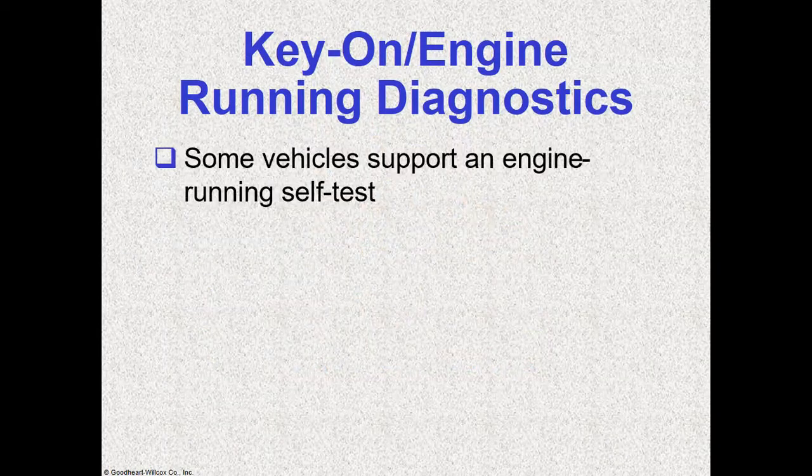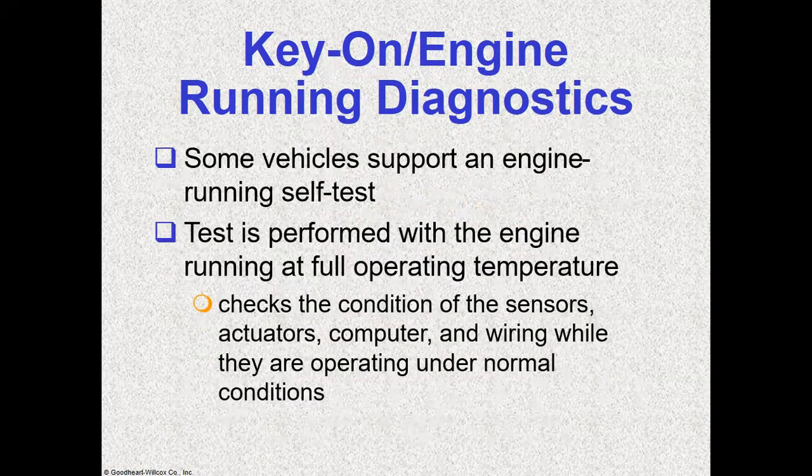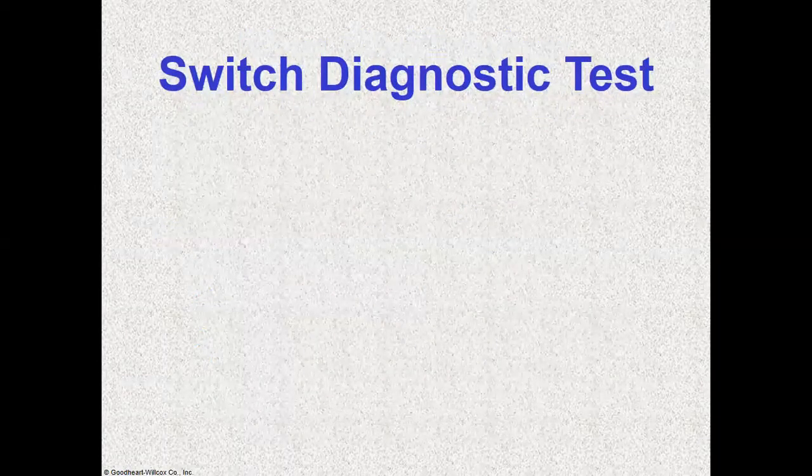Key on engine running diagnostic. Some vehicles support an engine running self-test. The test is performed with the engine running at full operating temperature. So you check the condition of the sensor, actuator, computer, and wiring while they are operating under normal conditions.